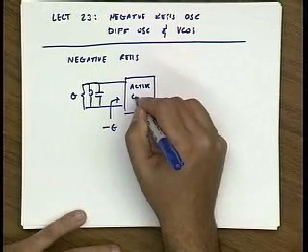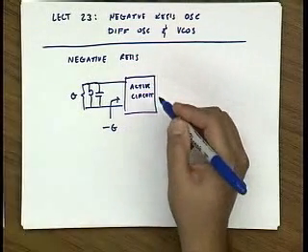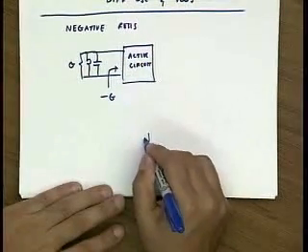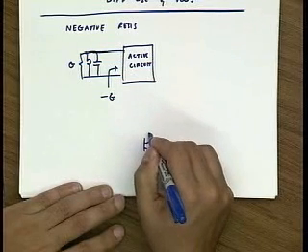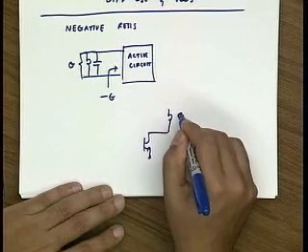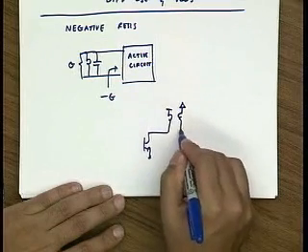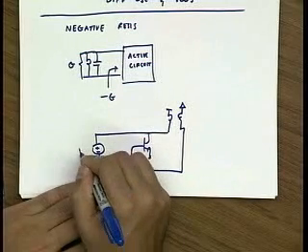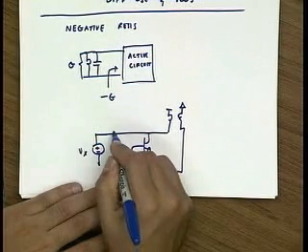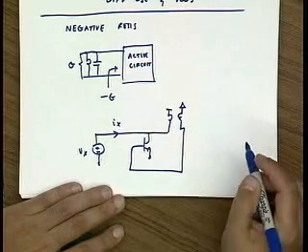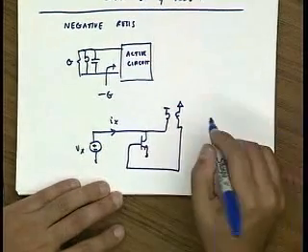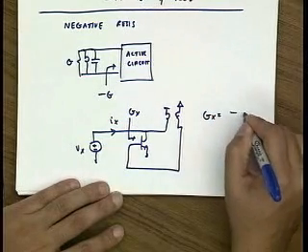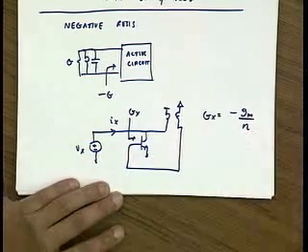And in fact, what we showed was that for the negative resistance oscillator like this, we take a transformer at the output, an inverting transformer, and hook it back up into the input. If we probe the circuit with a test source Vx and look at the current Ix, we find that Ix is actually negative. In other words, the input conductance, Gx, is minus the Gm of the transistor divided by N. Okay?